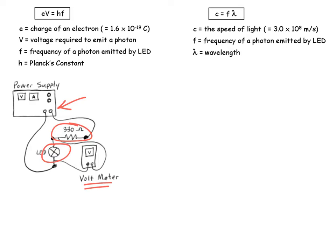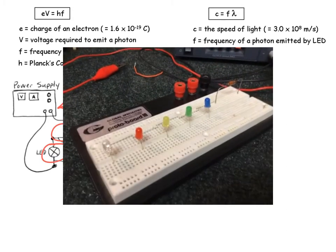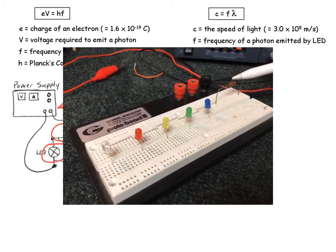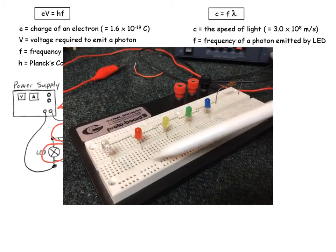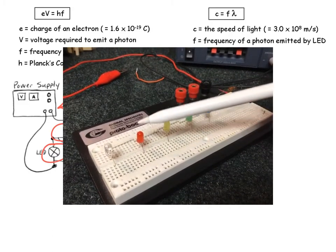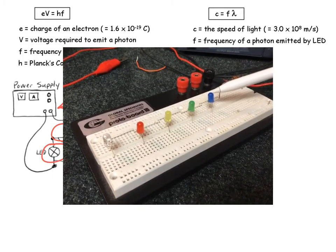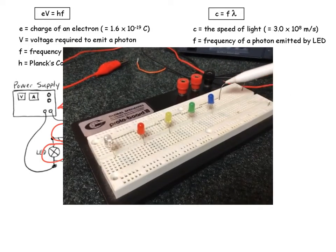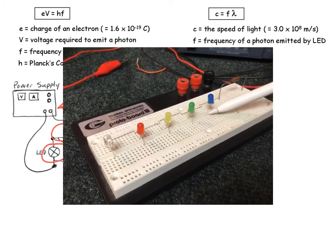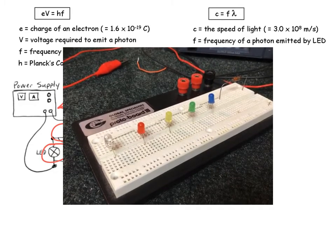Now, what would this look like? Here's a circuit board that contains the components we need. We have our resistor, 330 ohms, and we have a series of different LEDs of different color: blue, green, yellow, red, and this one is infrared. And what we're going to do is hook up each one of them in series with the resistor one at a time, and measure the voltage across this to just barely light the light.